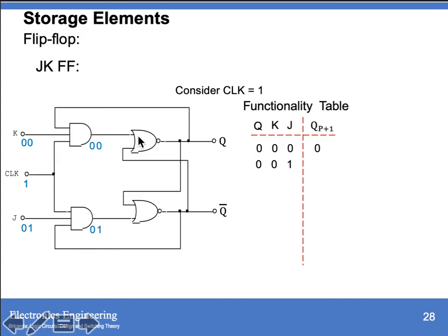So we have to first determine what is the second input of your NOR. Since it is equivalent to 1, this NOR will generate an output of 0. If this is 0, now we have a second input of your first NOR as 0. So we have 0 NOR 0, so that is equal to 1. And if we have 1, 0.